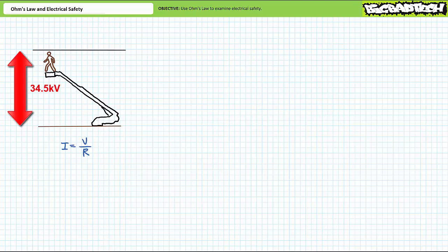First, everything is a conductor. However, some conductors are better than others. A saltwater-soaked person is an especially good conductor with low resistance. Second, a metal platform is also a low-resistance conductive path connected to Earth, something we often use as a reference for voltage measurements. Third, the wire is high voltage. The magnitude of this voltage is often made with reference to ground, that same plane the worker is connected to via the metal platform. If the worker touches the wire, there is a high voltage differential across a low-resistance path and substantial current will flow. The magnitude of this current via Ohm's Law is directly proportional to voltage and inversely proportional to resistance. If the voltage is high and the resistance is low, the current will be extremely high.